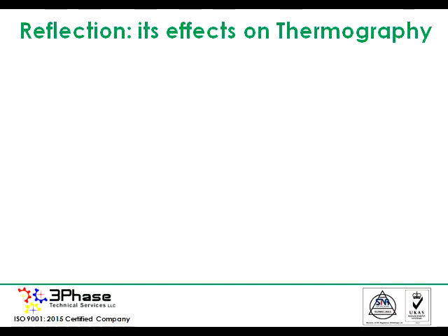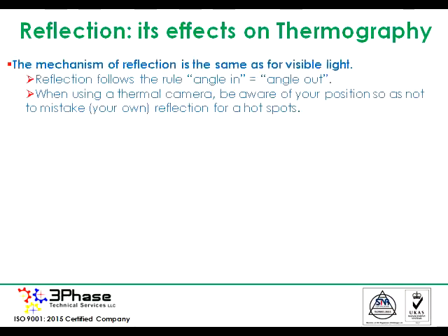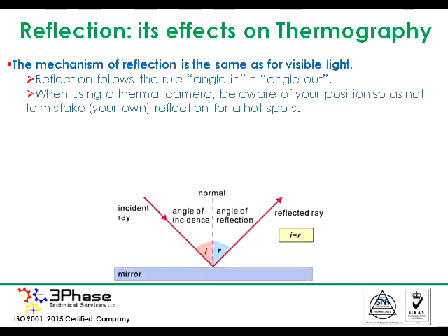Reflection, its effects on thermography. The mechanism of reflection is the same as for visible light. Reflection follows the rule angle in is equal to angle out. When using a thermal camera, be aware of your position so as not to mistake your own reflection for a hotspot.